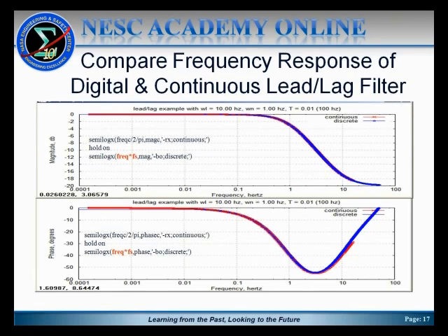So you'll notice in both the upper plot and the lower plot, the second semilog x command, which plots on a semilog scale, the frequency that's shown now in red. I've actually plotted the FREQ parameter that came out of the DFT, discrete Fourier transform function, now multiplied by the sample frequency fs. That converts that normalized frequency, which is frequency divided by fs. If you multiply by fs, you get basically that frequency converted back to hertz instead of normalized frequency.